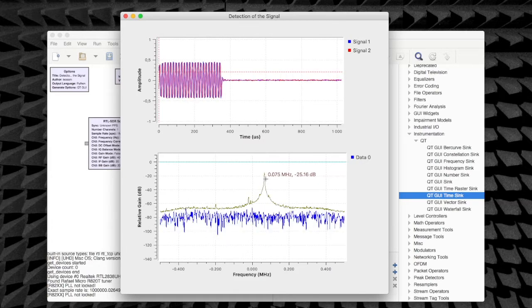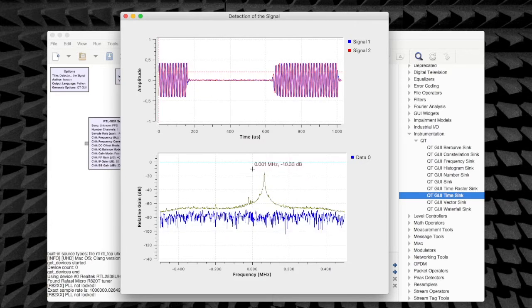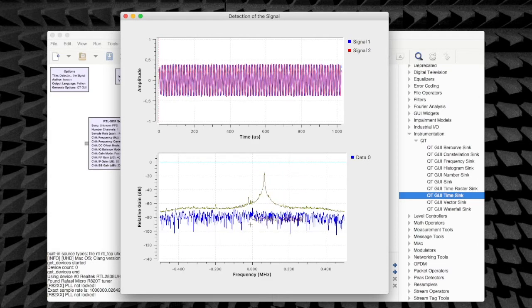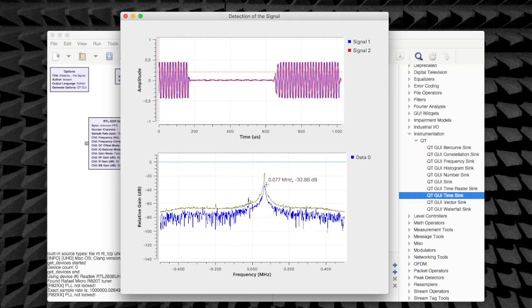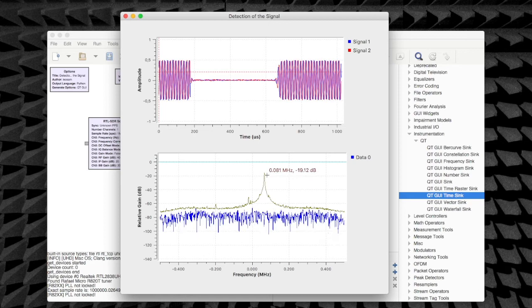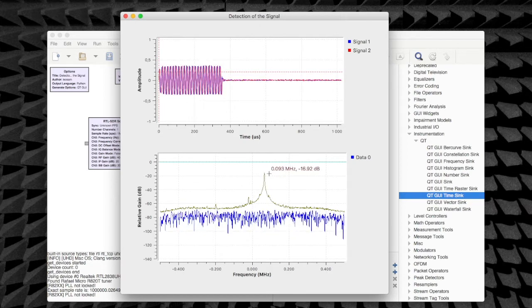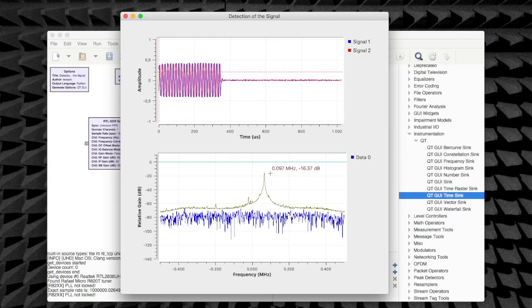But what I'm going to do rather is I'm going to still concentrate on my center frequency, which is 433.92, given here at the 0 megahertz mark. And I'm going to consider a little bit more, about 80 kilohertz to both sides, in order to do my filtering correctly.